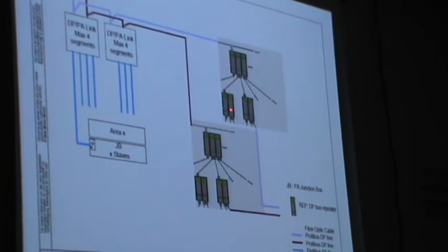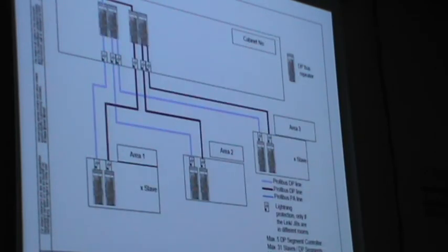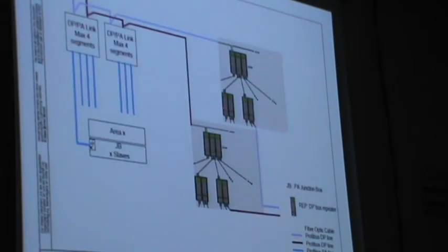So one repeater will be installed in that 1 JB, and from there all the instruments are looped. So there will not be any disturbance in the communication. For increasing the speed, we use the repeaters, and from this repeater the field signals will be communicated. So from here, it will be distributed to the field also.